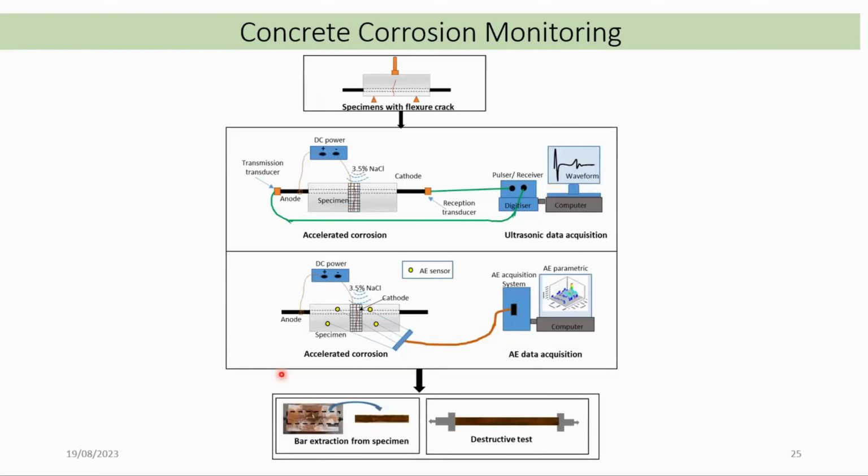Now, with all this knowledge that we have got so far, we are trying to do a bigger problem. In the bigger problem, we are trying to monitor the steel bar corroding while it is embedded inside concrete. So as of now, we have done monitoring when the bar is outside. Now we have embedded the bar in concrete, and we are trying to find out whether all these corrosion activities can be picked up. We have done this experiment in a few different ways. First, monitoring through piezo-based excitation. In this mode, it is called guided wave ultrasonics, because the wave is guided in the concrete by the steel bar. So the wave doesn't go everywhere in the concrete, but it is going only through the steel bar, and the steel bar acts as a guide.